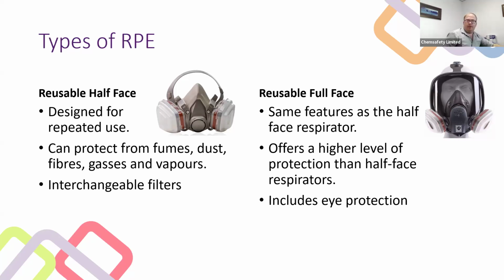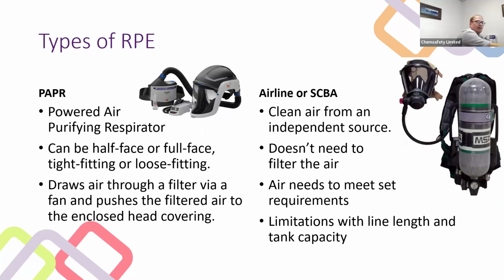Our next respirator we have is a powered air purifying respirator, or PAPR for short. And this is another step up in terms of cost, but also another step up in terms of the level of protection that can be achieved. So it can either have a half face unit or full face unit. They can be tight fitting or loose fitting. Now this one here is a loose fitting.